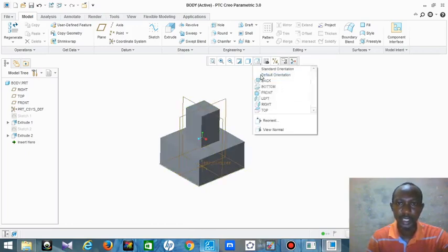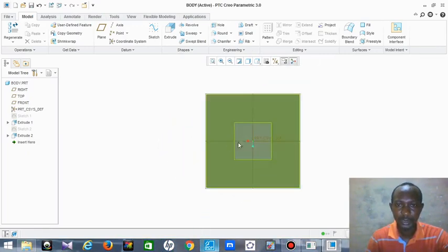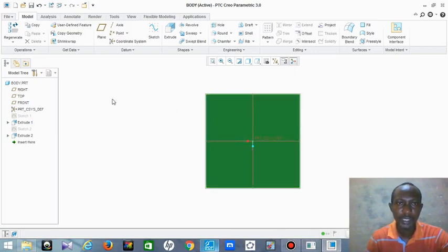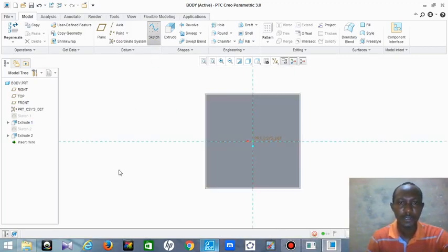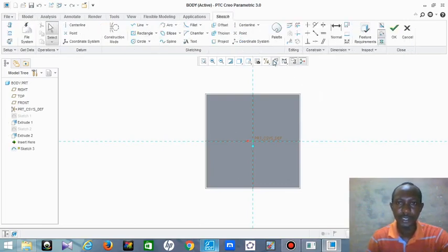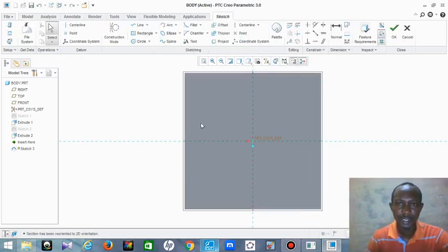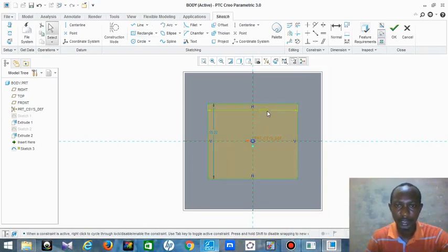So all I need to click now, I need at the bottom, click on the bottom. So I need a circle under it. Okay, click on that bottom also. You highlight it, click on sketch. So it's already facing us. You don't need to click on this again. If you click, it's already facing us. Then you go to your rectangle with center, click on it, you middle click, then you double click to set it. Okay, so I need a circle here, not this.